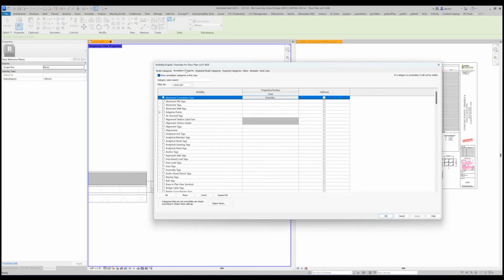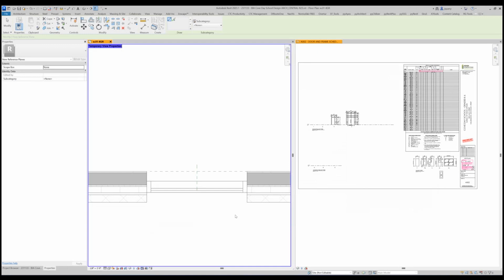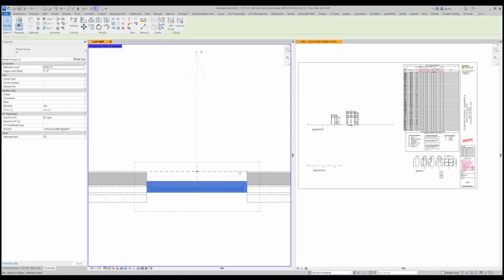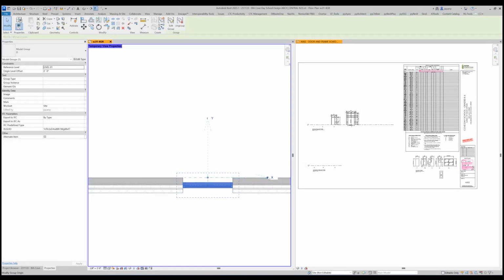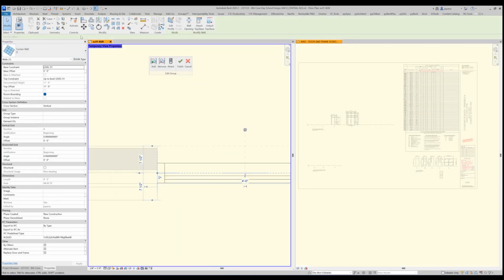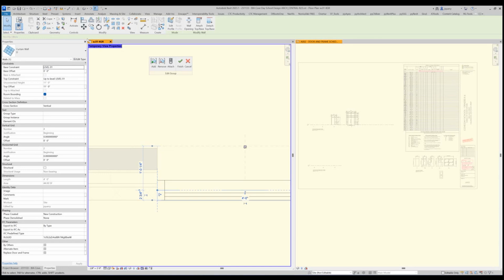Turn reference planes on. And I'll show you another secret tip to speed this up even faster if you want at some point. Here, I'll do this. And I will rotate this around because we want it to point to the exterior side of the wall. And then let's move this to 3 inches away, right? That's what we decided to start with at least. I think so.